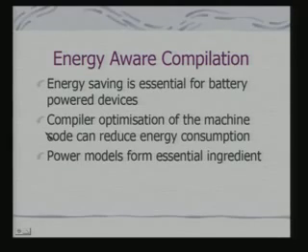And this optimization is not that obvious. In fact, I had already talked about how I can choose a set of instructions for doing a computation which consumes the least number of cycles. That gives me efficiency in terms of time. But it may not give you efficiency in terms of energy. So the first kind of optimization in a way is universally valid.